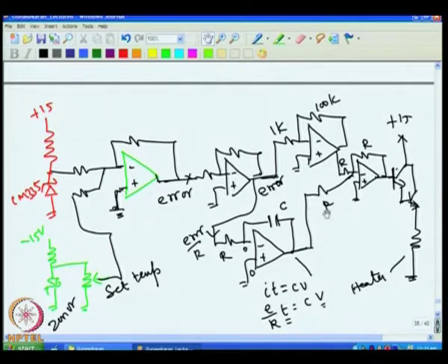If we add the integral time constant, then since the gain is less, if proportional action alone was there, you would have got a lot of error. Because of integral action, the error also goes off and the system stabilizes without any oscillation. So, the gain should be set correctly like that.